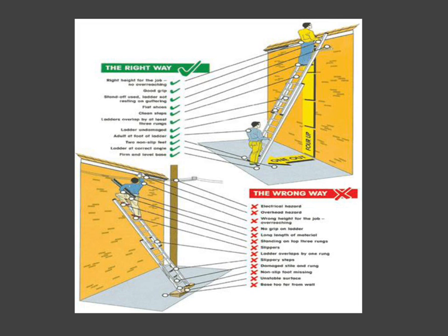Should he be going to go up on the roof, that ladder would have to extend 3 rungs or 3 feet above that roof line so that he would have something to hold on to when he got off of the ladder.